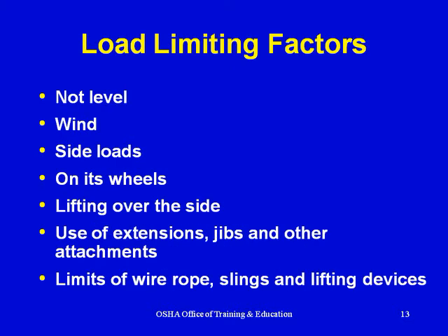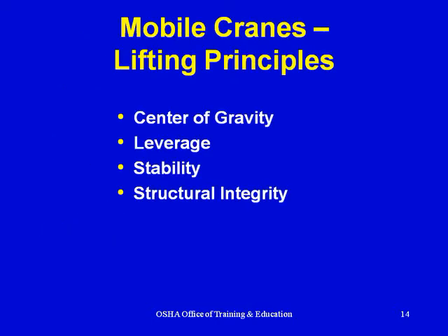Load limiting factors: not level, side loads, on its wheels, lifting over the side, use of extensions, jibs, and other attachments, limits of wire ropes, slings, and lifting devices. Mobile cranes, lifting principles: center of gravity, leverage, stability, structural integrity.